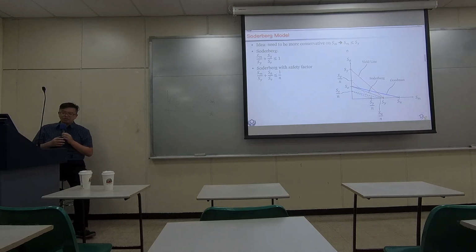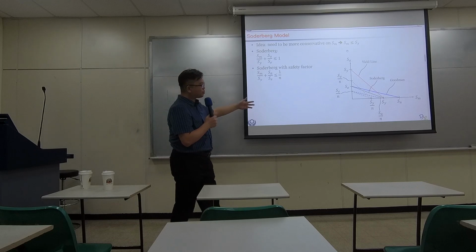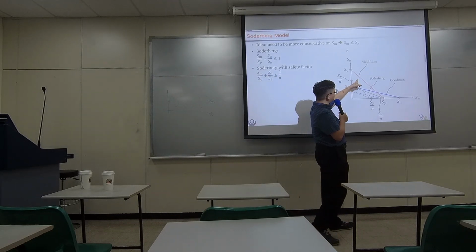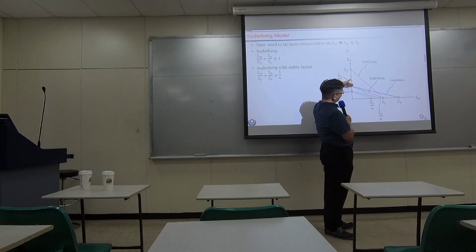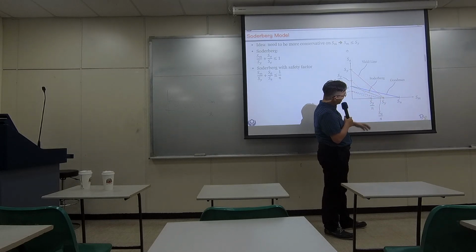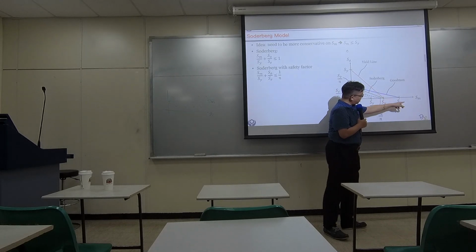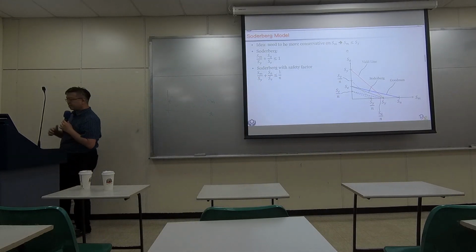Okay, these three are the most famous linear models. We first start with the yielding line, and then because of fatigue, we believe we should be more conservative on the amplitude part. And Goodman and Soderberg have different ideas about the upper limit for the mean stress part. Okay.